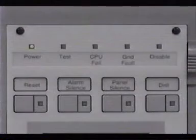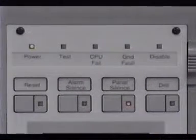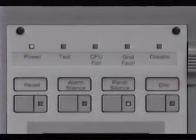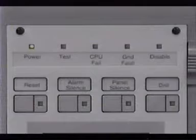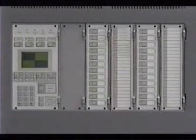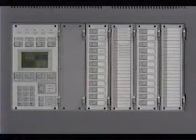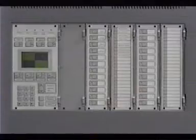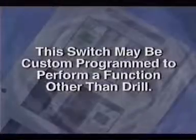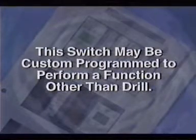Pressing the panel silence switch LED turns off the panel's internal buzzer. Additionally, viewing all queue messages automatically silences the buzzer and lights the panel silence LED. Pressing the panel silence and alarm silence switches simultaneously activates the system's lamp test function. This tests the system's LEDs as programmed. Pressing the drill switch activates the fire drill function. Note that this switch may be custom programmed to perform a function other than a drill.